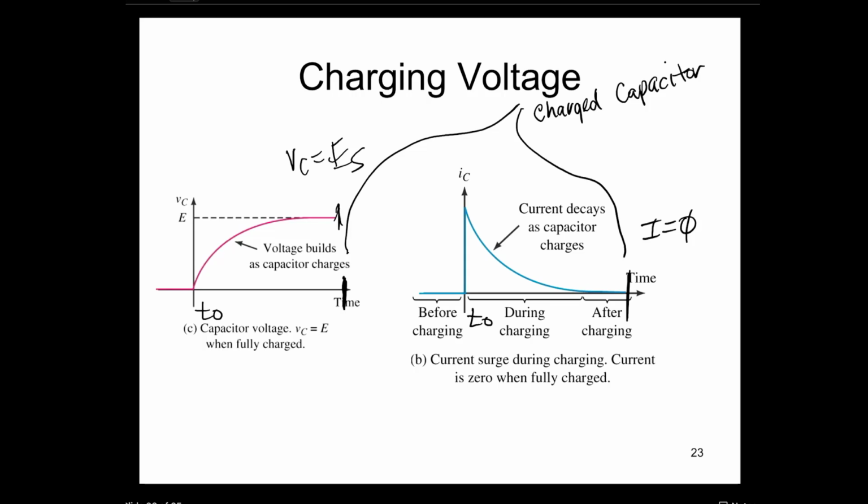But here's where we're going to pull something from this whole relationship. If we look at the moment the voltage is connected, right here, this is where the capacitor is showing its reactance. It's reacting to that change in voltage. It's opposing that change in voltage. It's accepting the change of current, you could say, but it's opposing the change in voltage. So what do we see? We see an immediate change in current going right up to an I max value.